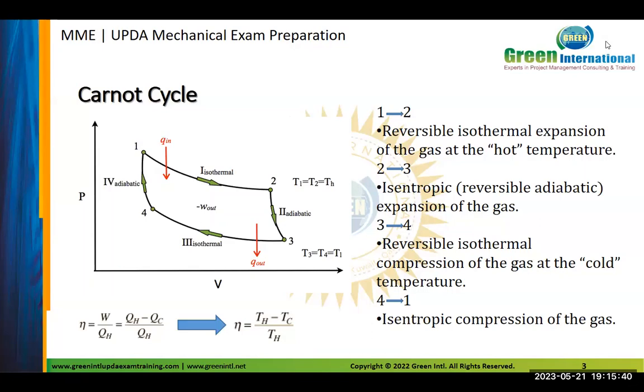Also for calculation of any required quantity, like work required, heat required, heat rejected, work consumption, all these energy calculations, related to work or heat, can be calculated according to the concept of the difference between two enthalpies. You know the enthalpy for the first state and the second state of the process. So whether this represents heat or work, whatever, the calculation is equal to the difference between the enthalpies of these two points.